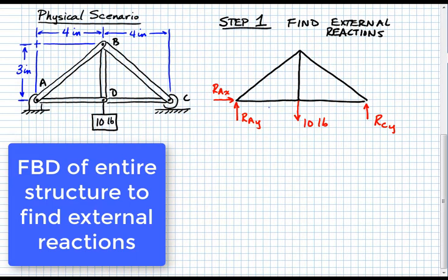The critical dimensions that we need to know here: we need to know that this is 4 inches across from there to there, and that that's another 4 inches across from there to there, in order for us to use this free body diagram. And then to make it complete, we'll stick some axes on here also, our X and Y axis for those two things.